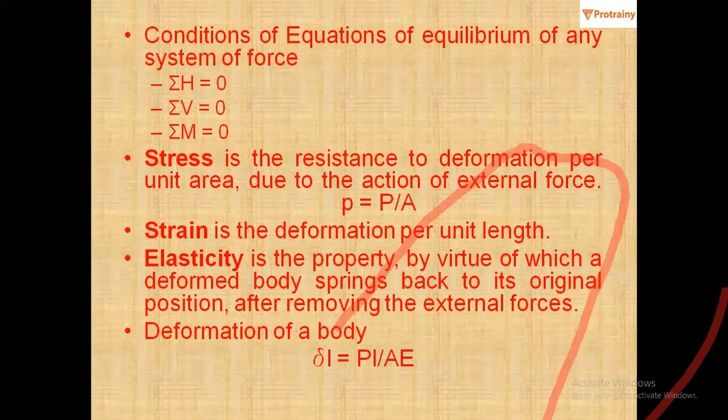ठीक है ना? Stress is the resistance to deformation per unit area. That is what a stress is, due to the action of external force. और उसका expression for that is small p is equal to capital P upon A. जो force है उसका जो भी magnitude है, if you know the magnitude of that force, then you have to divide it by the area on which this force is acting. That is what stress. Then comes strain.